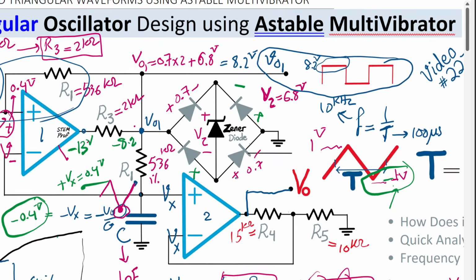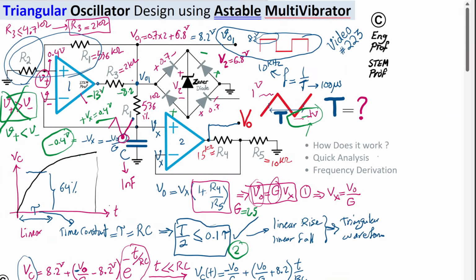Okay, so I'm going to write it here then. The value of R2 is going to be 27.4 kilo ohm, and it will be similar to the other resistors. It should be 1% tolerance. So all resistors in this circuit, 1% tolerance or even better.